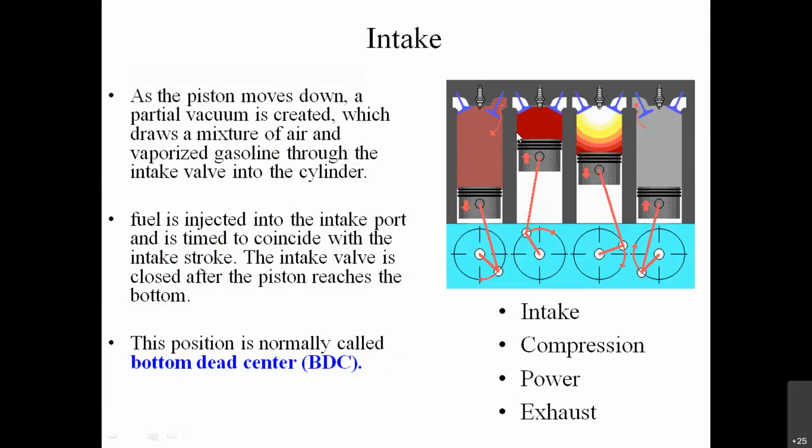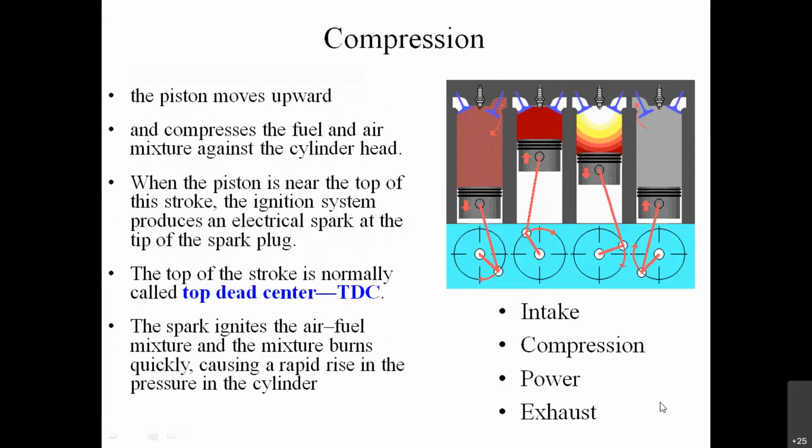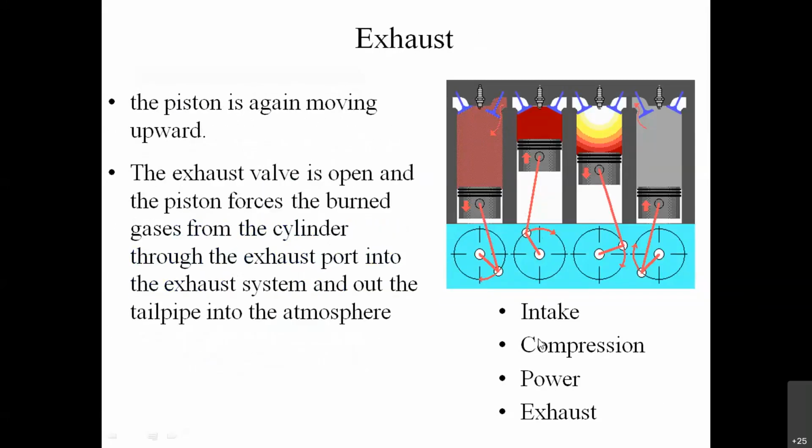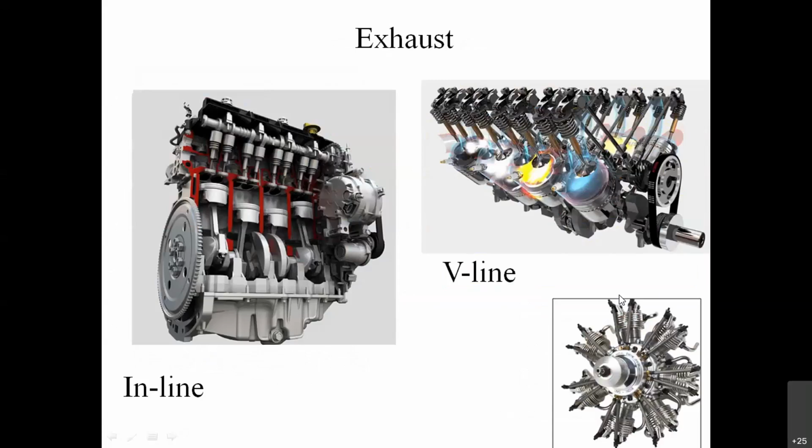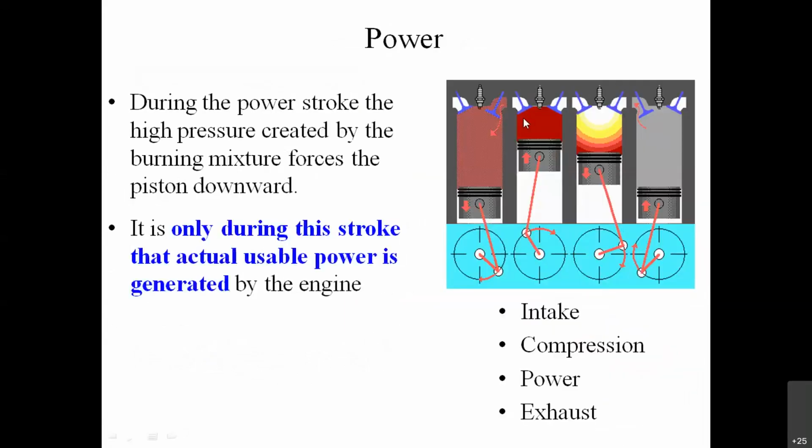In the next stroke, the piston starts moving upwards, so compression of the air-fuel mixture takes place. During that, the crankshaft rotates through a further 180 degrees. Because of compression, a very high temperature is created there.